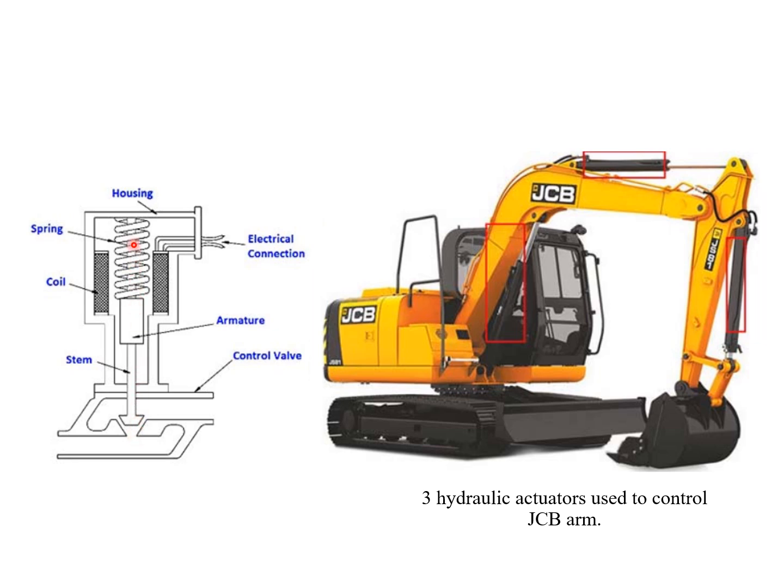And you have the spring here, which will return the armature to its default position whenever the coil is de-energized. You also have the electrical connections, which provide power to the coil, and the entire valve has a housing which encases and protects the internal components. So when the solenoid is actuated, the coil magnetically lifts the armature, allowing the fluid or gas to pass through. When deactivated, the spring pushes the armature back, stopping the flow, right?